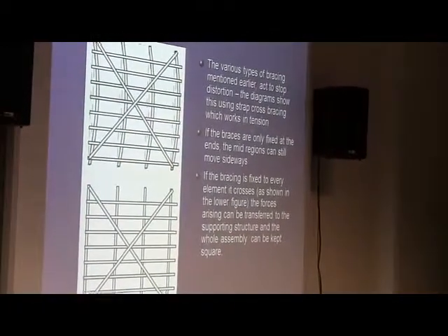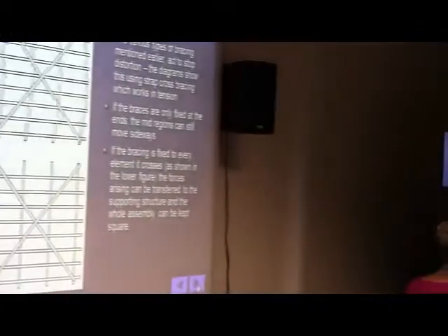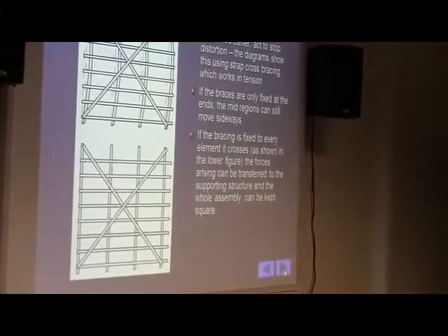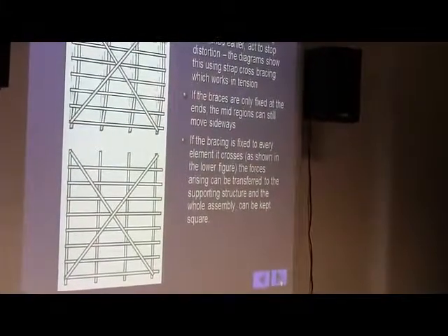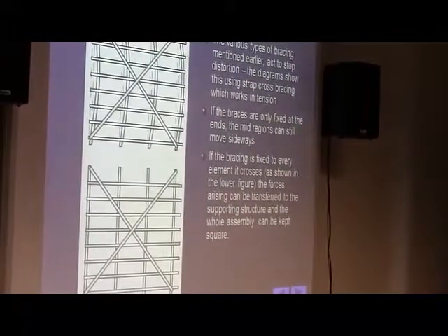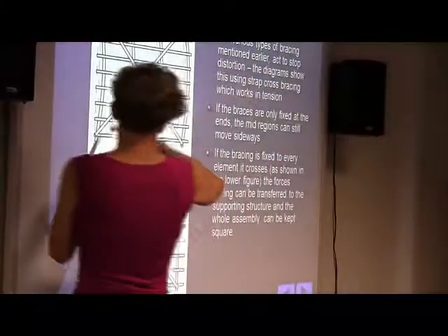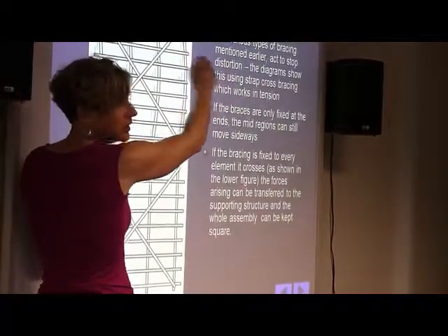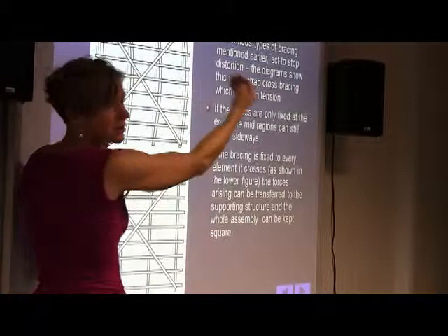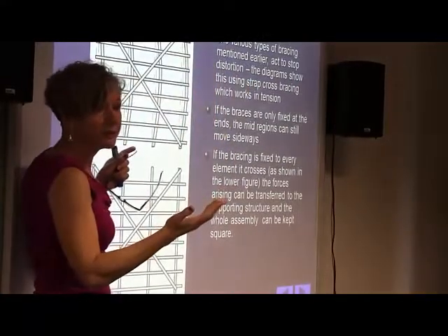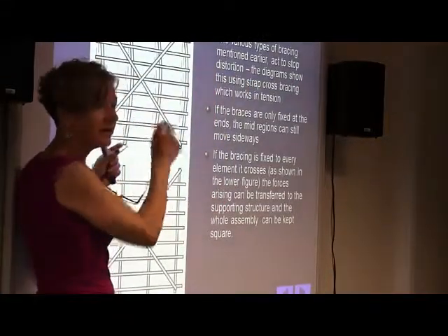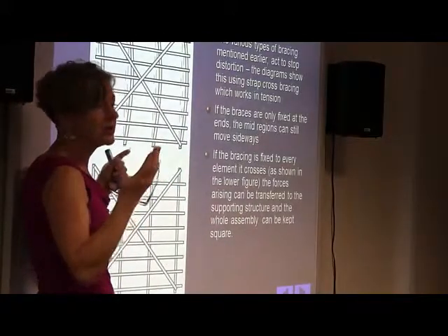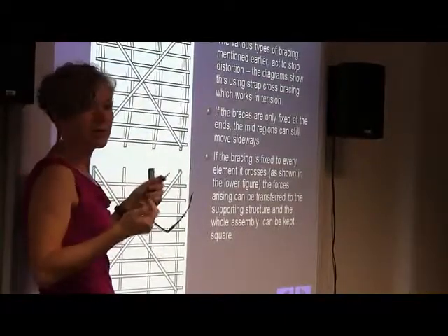So that's illustrating, again, the diagonal brace. So when you have diagonal bracing, obviously the wind comes from all directions, so you have to have two. One brace in this direction. When the wind comes from this direction, it will go into tension. That's good. But in the other direction, the wind in the other direction will put it into compression. And these members tend to be slender. They might just be a steel strap that's 1 or 2 millimetres thick. So if you put it into compression, it just buckles immediately.